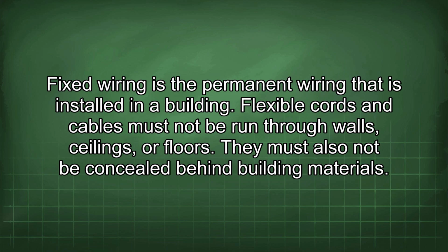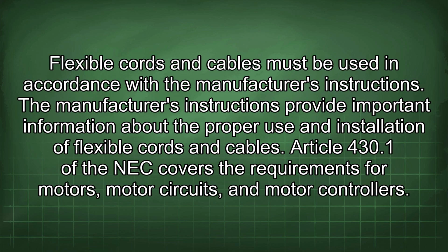Flexible cords and cables must not be run through walls, ceilings, or floors. They must also not be concealed behind building materials. Flexible cords and cables must be used in accordance with the manufacturer's instructions. The manufacturer's instructions provide important information about the proper use and installation of flexible cords and cables.